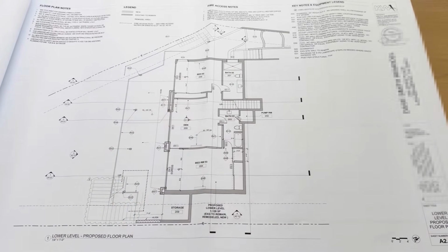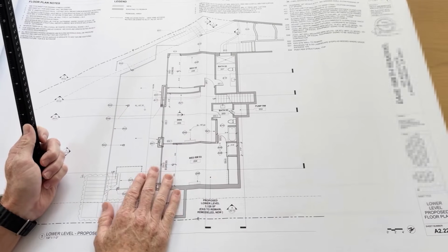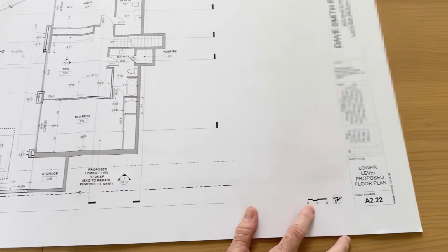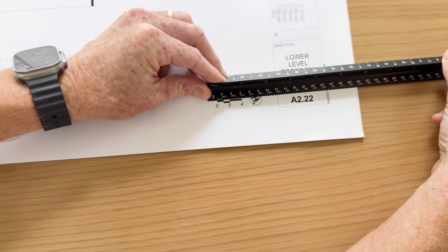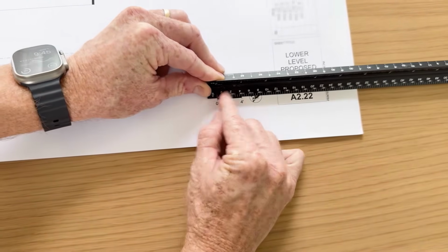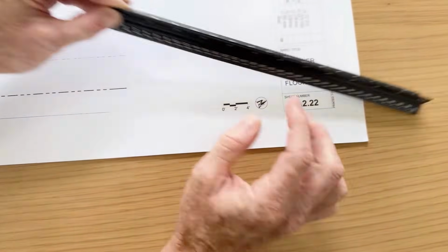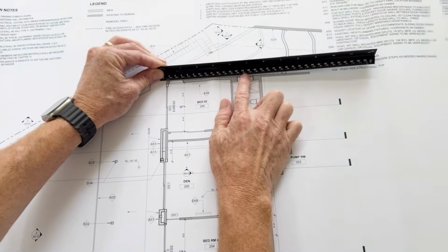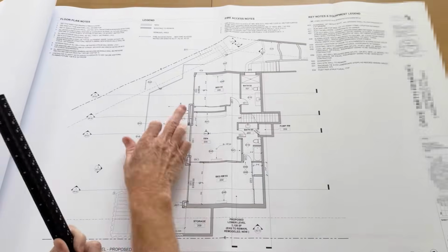And the other thing that we want to talk about here is any new walls or any walls that we want to add. Typically what the architect is going to do is, we've got our scale down here, okay? If you use whatever arbitrary tool you want, if you want to use the 3/16 mark, 3/16 up to basically 4 means 4 feet. So anytime you're measuring or laying out, we want to follow that simple addition to be able to determine wall layout and spacing.